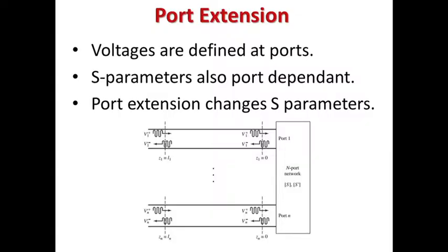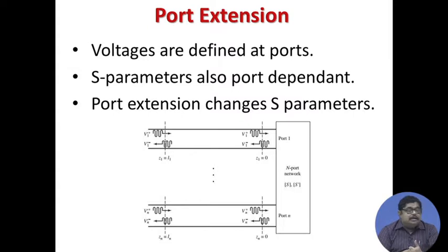So, voltages are defined at ports. S parameters are also port dependent. Now, if I change that port, that means if I extend that port, that terminal plane, then I need to redefine the voltages and the S parameter will also get changed.